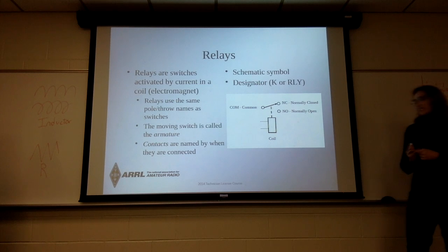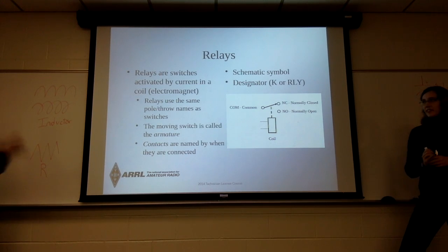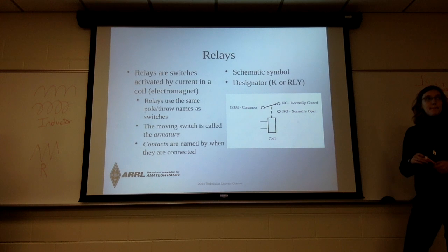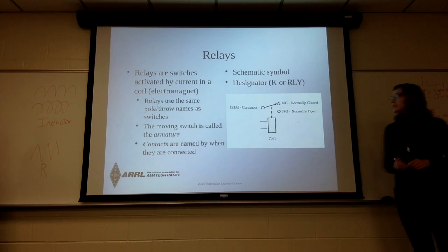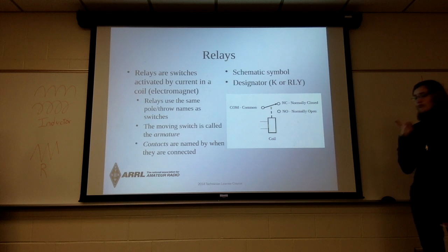Relays are often used in the final output stage of a transmitter because you want to be able to switch the antenna between transmit and receive. So you want to be able to switch between the high power amplifier and the receiver. And we just have one relay that, when you key down the microphone or your Morse code key or whatever, automatically does that switching for you instead of having to unplug it and plug it in. That gets real old real quick. That's it for relays.